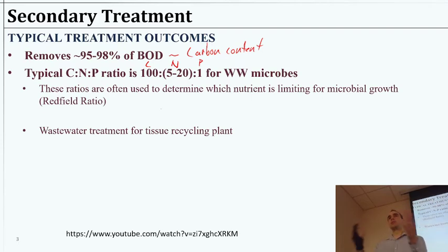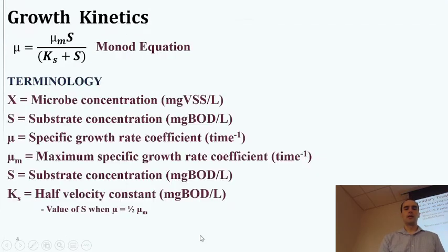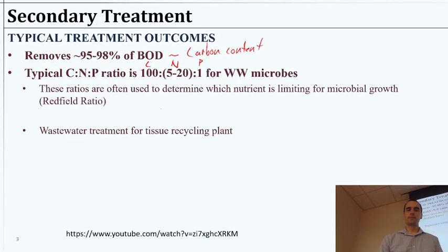You could look at that to what corresponds to the human body, if you were to kind of totalize the atomic ratios there. And for wastewater, it's just pretty handy to consider that, because in some cases you may have an issue where you need to add one or the other, or perhaps in tertiary treatment you're trying to remove nitrogen, and so you have to make sure that it's not limited in carbon and give it the right conditions so that you get a process that will take nitrogen and kind of consume the majority of it.